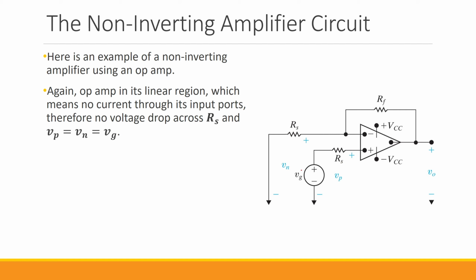So now how can we analyze this circuit? The first thing that we do is we write down the constraint that we have. We have Vn equals Vp and then In equals Ip equals 0. So we have In here, we have Ip here, and then Vn and Vp are labeled like this. They are considered as voltage rises from a common or reference node, which is these three lines, and conceptually it looks as if they are connected all with a wire.